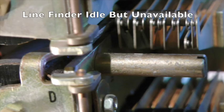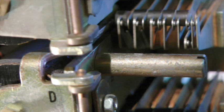If the secondary winding of the D relay is energized, it means that the start chain path through this line finder is grounded, indicating that there is a dial tone request currently being processed by another line finder, or that there is a queue of dial tone requests waiting to be served. This line finder is considered to be idle, but is unavailable to serve new dial tone requests until the D relay releases. The D relay releases under two conditions.